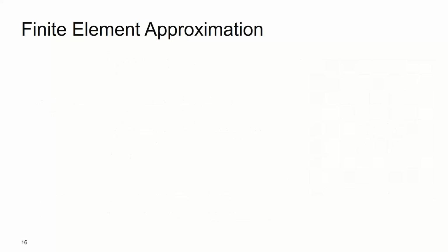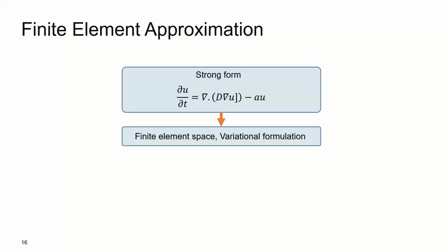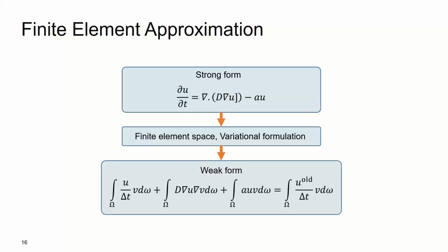In finite element terminology, this is really important because this is what FreeFEM deals with. In order to use tools like FreeFEM or FEniCS, that we already had a webinar on, you really need to learn this mathematical background, which is also very easy to get. We call the partial differential equation we want to solve the strong form. Then we apply a mathematical technique, a variational formulation and function space, on that. And then we get a weak form, a form that looks like this. I will quickly show you how it is derived.